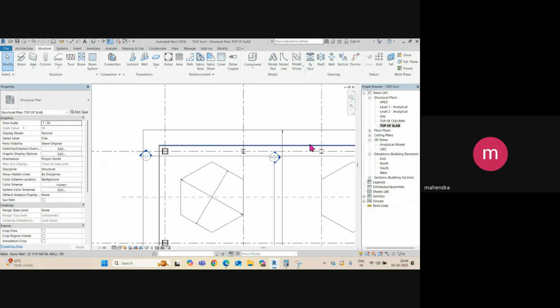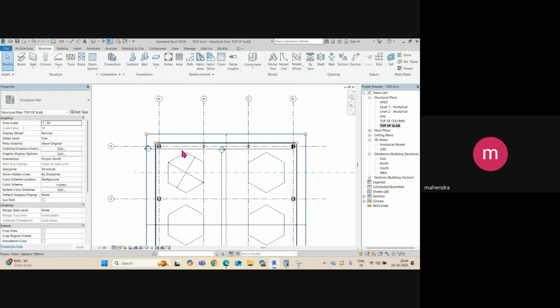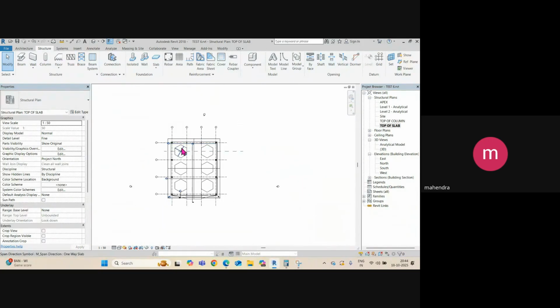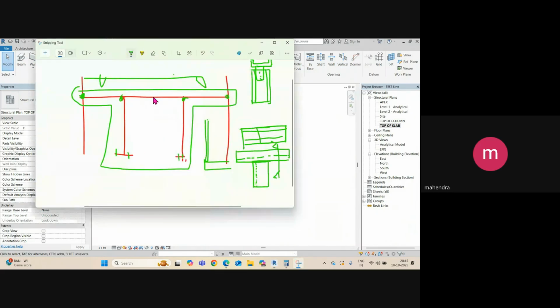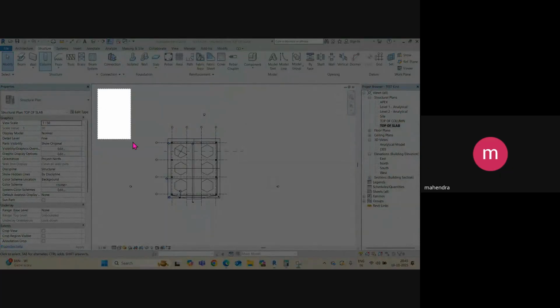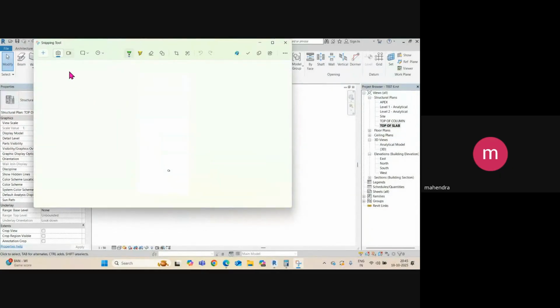Okay, so I will create the drawings for the column base plate layout plan. For this building we will create some drawings first. So you should list out the drawing numbers, how many drawings you require for this structure. The first is your base plate layout plan. In this we are just giving the set out dimensions for each and every base plate column. Then you can add an isometric view here also, so your structure isometric view you can provide here.